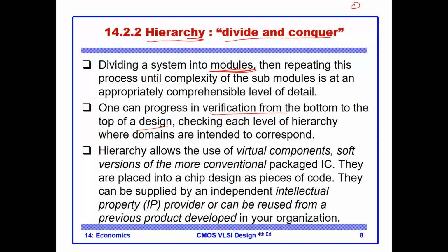So for example, if you have your design split like so, you would want to verify these components at the bottom, the smaller components, and then you go to the ones that instantiate them, and then the one on the top. In fact, if you verify those components, typically their verification and testing is easy, and then the upper ones become a simpler verification, and the focus will be on connectivity because you have done a good job on functionality at those leaf modules. Okay, so you would want really to start from the bottom to the top, and that should facilitate